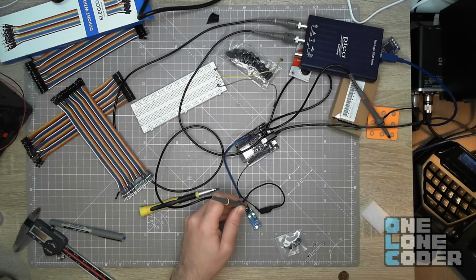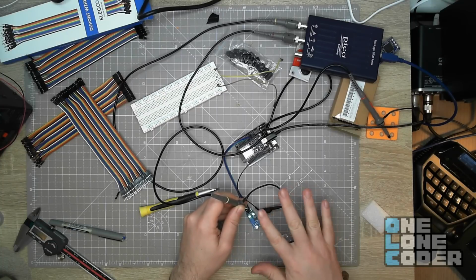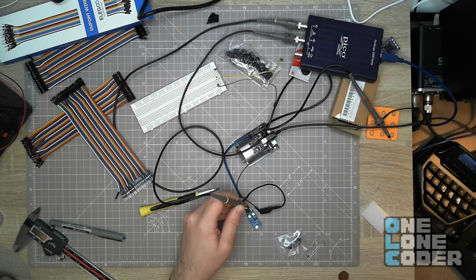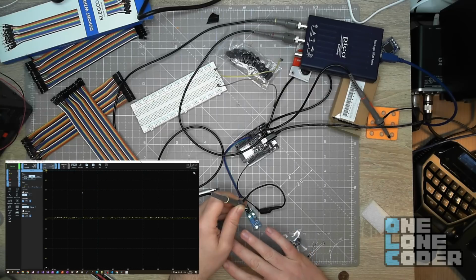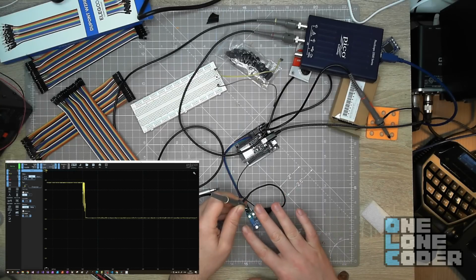That's good. I just wanted to confirm what was going on with the photodiode using my picoscope. It's a USB-based oscilloscope. It's okay for simple things like this. So I've got a probe on the output signal, and I'm just going to run my finger over the front whilst triggering it. And what I'm going to try and capture... There we go. So we can see it's actually really noisy, that digital signal there.